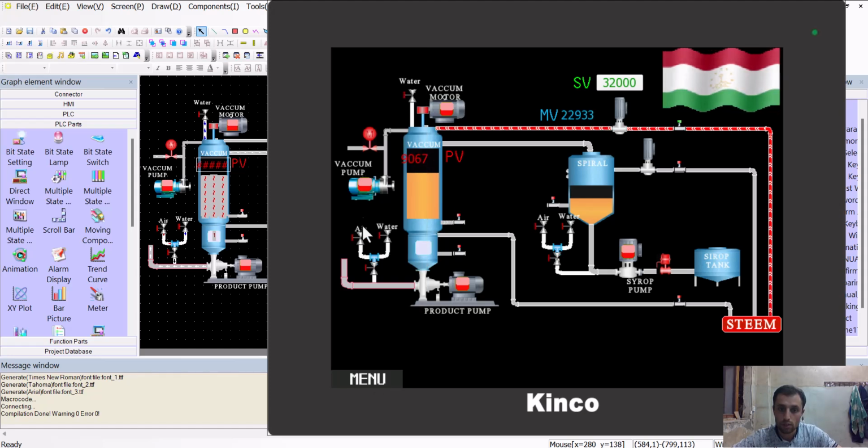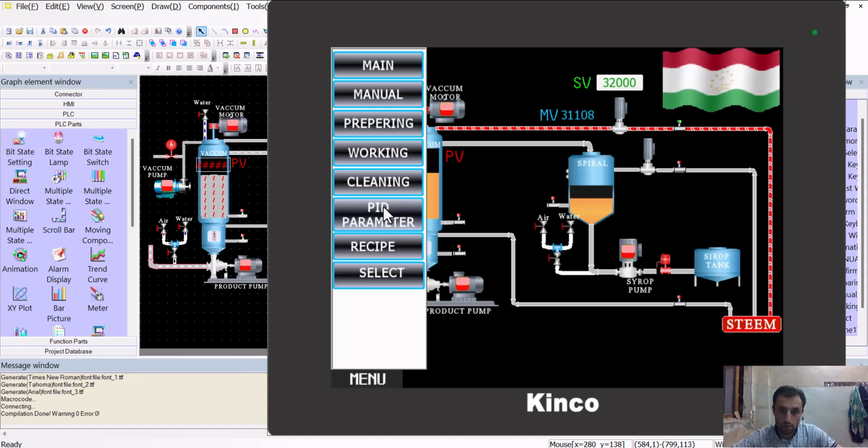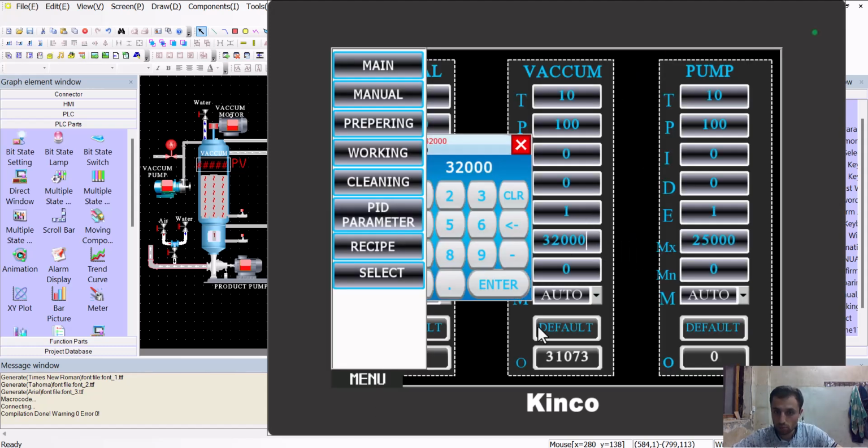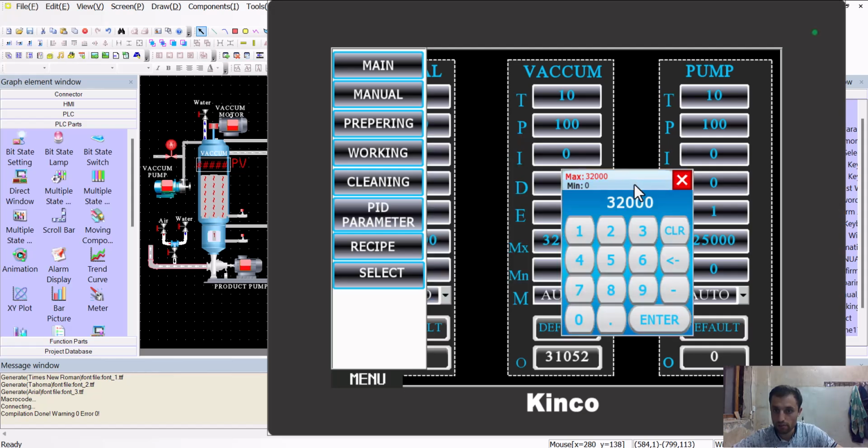Now you can change. If I decrease my input signal, it becomes minus. You can see here, this is my differential in the MV value. There is also another parameter we have there. This is the maximum value of your output MV value. If I decrease this to 20,000, this belongs to your scaling. For example, if I put 20,000, I just have this value.